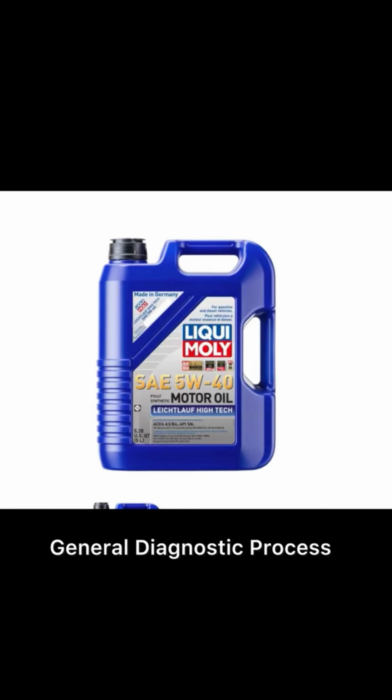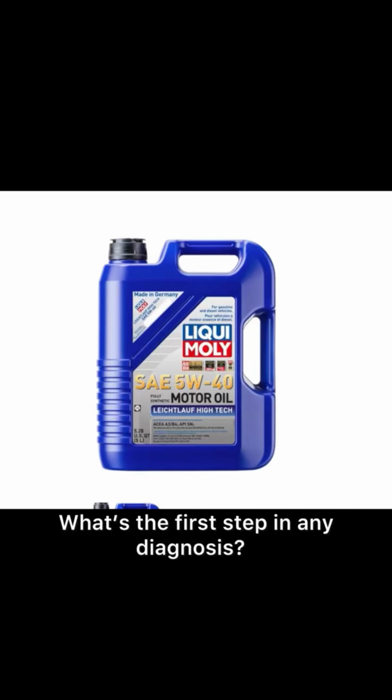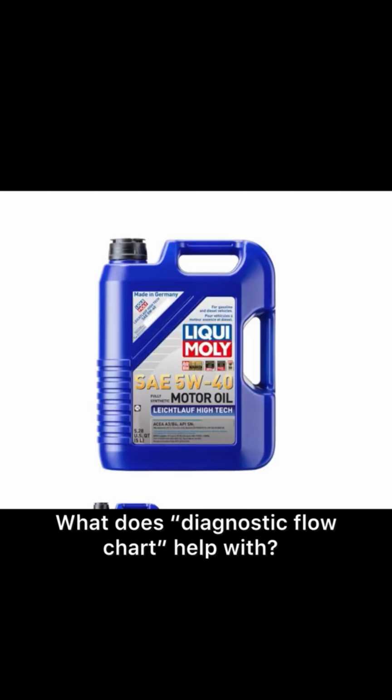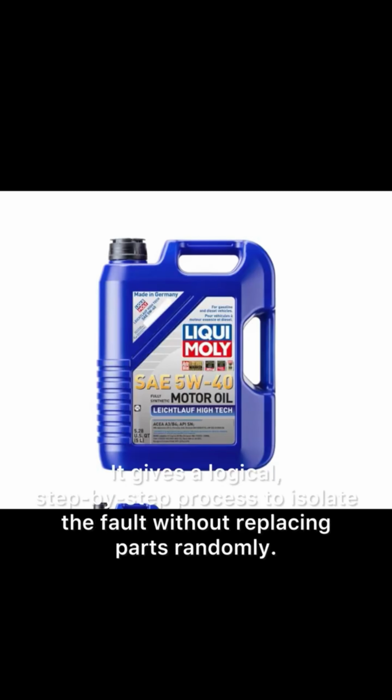General diagnostic process. What's the first step in any diagnosis? Verify the customer's complaint. Drive the vehicle and confirm the symptom yourself. What does a diagnostic flowchart help with? It gives a logical, step-by-step process to isolate the fault without replacing parts randomly.